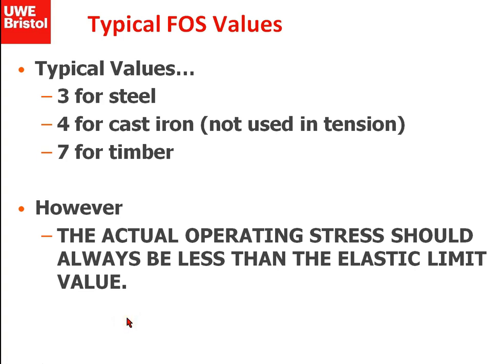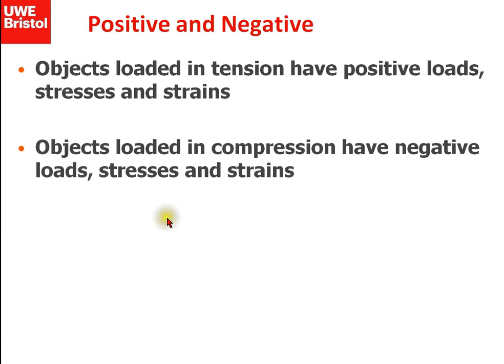Ideally, however, although we've mentioned the fact that we are going to measure our factor of safety in terms of the ultimate tensile stress, which is our highest stress value that we can experience, the other stress value that I mentioned relates to the elastic limit, which is the yield stress, and it's really up to the yield stress that you want to design anything for. So that's a lower stress value.